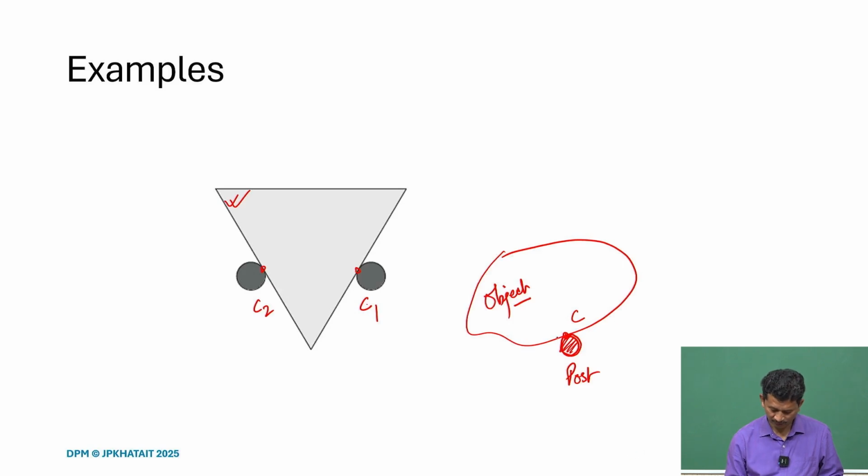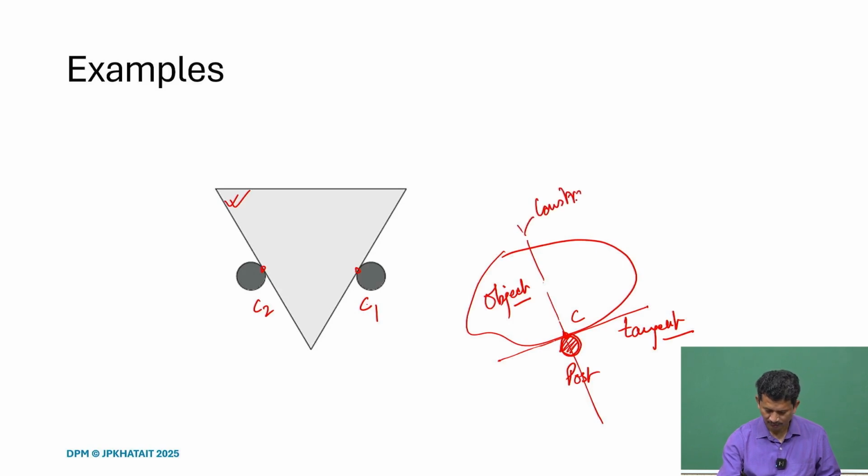So, what you see here is that we first try to find the tangent plane. So, this is the tangent plane, tangent in 2D case is a tangent line, right. The constraint will always be perpendicular to the tangent line, and passing through the contact points. So, this is the constraint line. Any motion along this line is not possible. But any motion along the tangent is possible, because it does not provide any constraint. So, this is tangent and this is the normal line, and this is the constraint line. So, be aware of this.